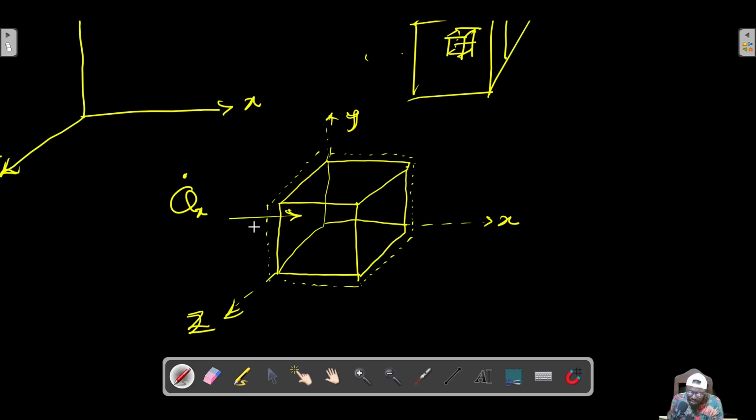Now, the heat flow cuts this particular surface and shows up at this particular surface. When it shows up at this surface, what will be the heat moving out of our control volume along the x-axis? We know this from calculus, it will be Q dot subscript x plus dx, because during the transfer of heat through the elemental volume, the change along the axis was dx.